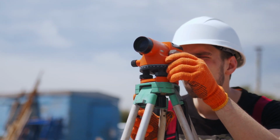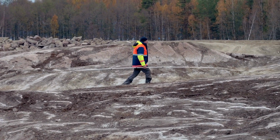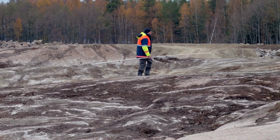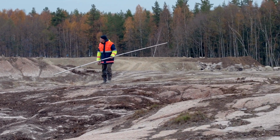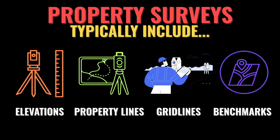Another type of drawing that often goes hand in hand with design drawings, both in level of detail used, as well as the preliminary phases of the project, are surveys. Surveys are produced by a licensed surveyor, and a survey illustrates information critical to the land on which the structure will sit. And if there's an existing structure that's being modified as part of this project, that is often also surveyed. The survey will include elevation marks at various locations, and by elevation I mean its position relative to sea level, as well as major property lines of the official parcel of land in terms of Department of Building records, along with grid lines, which we'll cover more in a later section, and other information pertinent to the site the project will be built on.